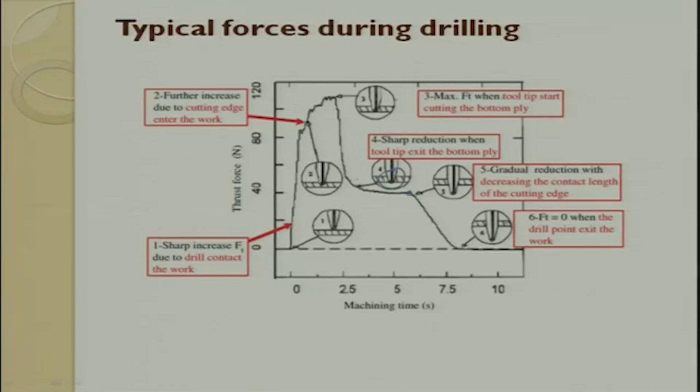During the process there will be a lot of delamination phenomena happening. There is a lot of workpiece material which gives resistance to the tool cutting. As it goes to the last ply, the resistance goes down; the stiffness offered by the workpiece to the tool goes down. At this point, with the same force, the tool tries to eject out, and when it ejects out it creates huge delamination. We are supposed to understand this and play with the forces such that delamination does not happen.